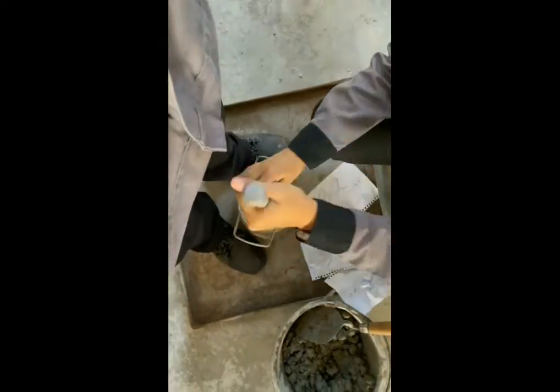The cone was removed immediately, slowly and carefully raised in the vertical direction. The height of concrete was measured in cm. As soon as the concrete settlement comes to a stop, the difference between the height of the slump cone and the height of concrete after settlement is the slump.